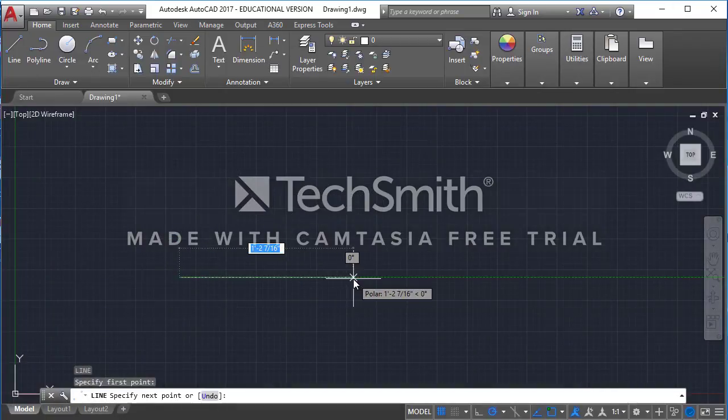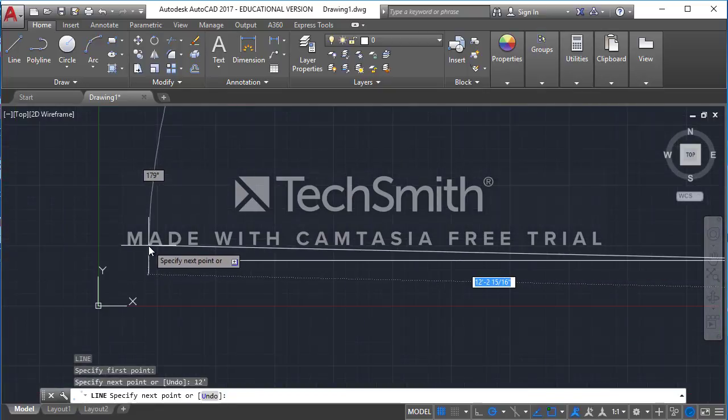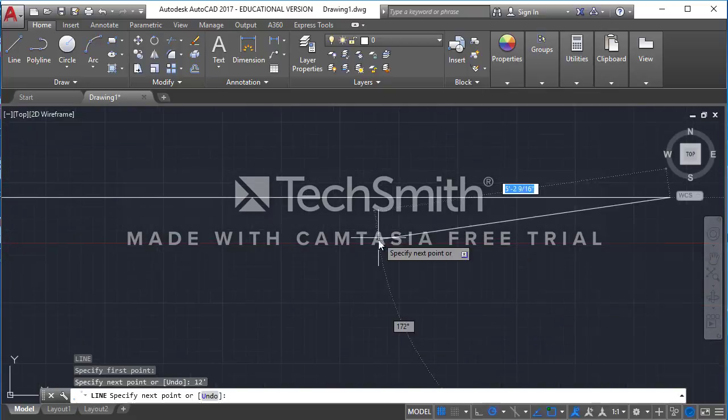Okay, so if I move my mouse over here to the right, I can simply type in 12, and I'm going to put in the feet symbol. Unlike Revit, which has moved on to a point where you don't need to put in feet and inches, in AutoCAD you will need to specify feet and inches. So if I want a 12-foot line, I will just type in 12 feet and hit enter. And you'll notice that I have a 12-foot line.